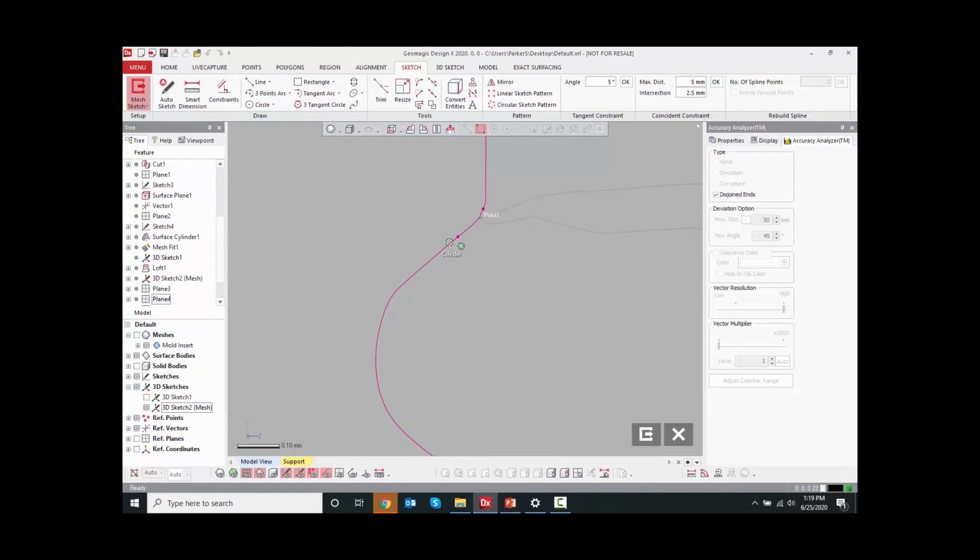So this is a lot of detail work just to get this thing right, but it's very simple once you have a good approach dictated in your head. So I'm going to, like I would inside of SolidWorks or other CAD, use my Convert Entities tool to convert that point of intersection, and then I can hide that sketch. And then I'm going to use my Line tool to fit a line to this section of the scan data.